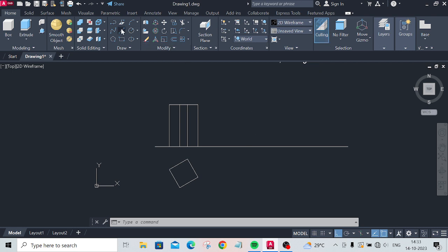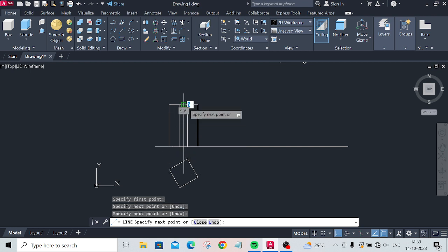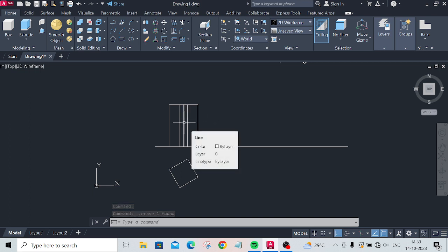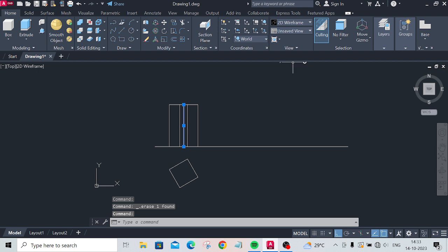Now along with this, you draw the center axis also. This is the axis, the center point of the prism. You project up to this. From here you draw another axis line. To differentiate that, you color that axis line. Okay, or make it a center line also. You know how to make it a center line? Or meanwhile we will color it. Double click on it and color it.